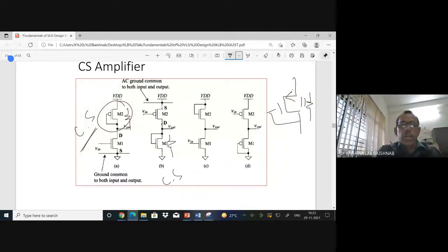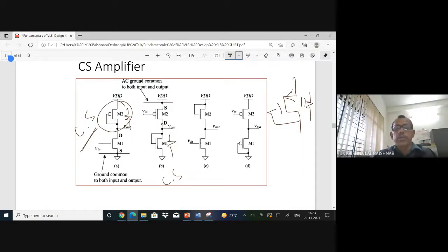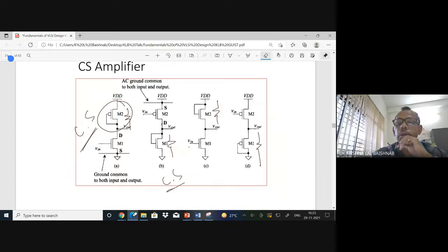Sorry. Now I understood that now this is a resistance, this is also common source. What is this? You see that this is a BJT, this is a resistance, again common source. This is a PMOS, this is a resistance, this is also common source. So all are common source amplifiers. So you can have different combinations where you can make your common source configurations.